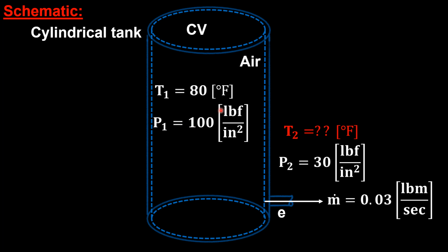Now this type of system is a control volume. Remember that systems have three types. We have a closed system, which does not allow mass flow or exchange of mass. So it's not a closed system, and it's not an isolated system. It is an open system. So we can use control volume or open system interchangeably.